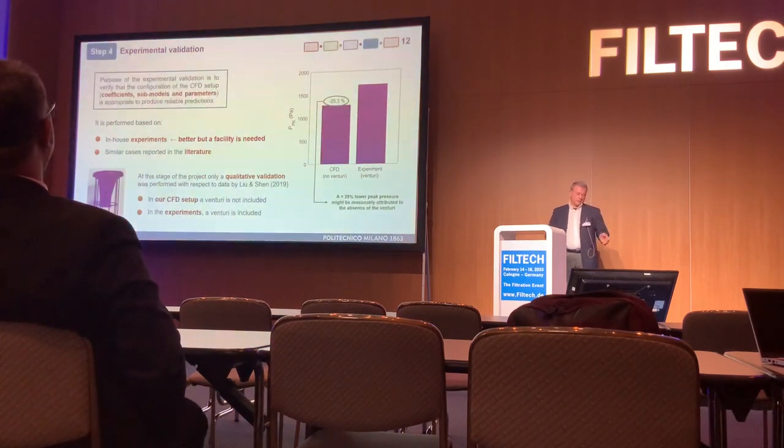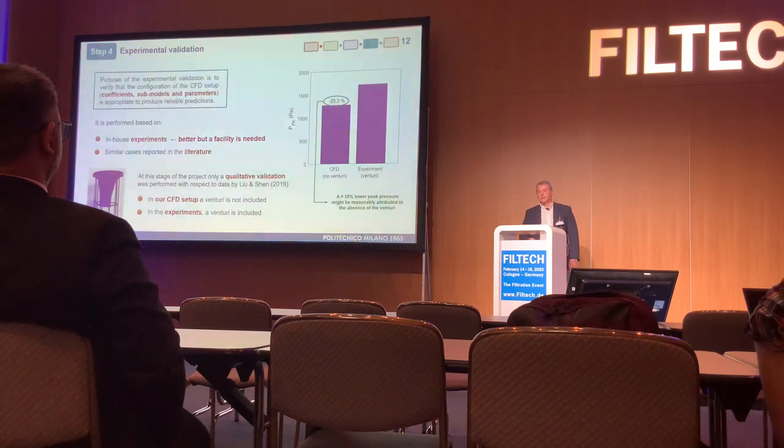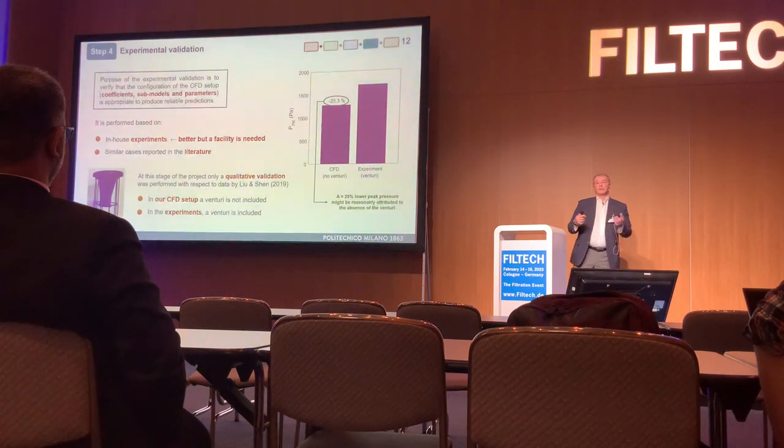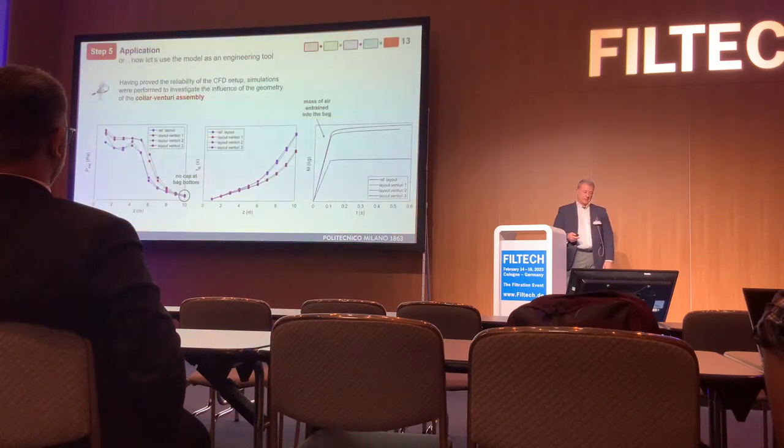And then we started to study some typical geometry. That is what is said for the experiment. We validated the computational fluid dynamics in some way by looking at the study of Liu and Chen of 2019, where we put exactly the same figures into the model and looked at whether they represented values close to those obtained experimentally by sensors. We found that the computational fluid dynamics system we chose was working, so it was representative of the figures effectively obtained. Why do all this?